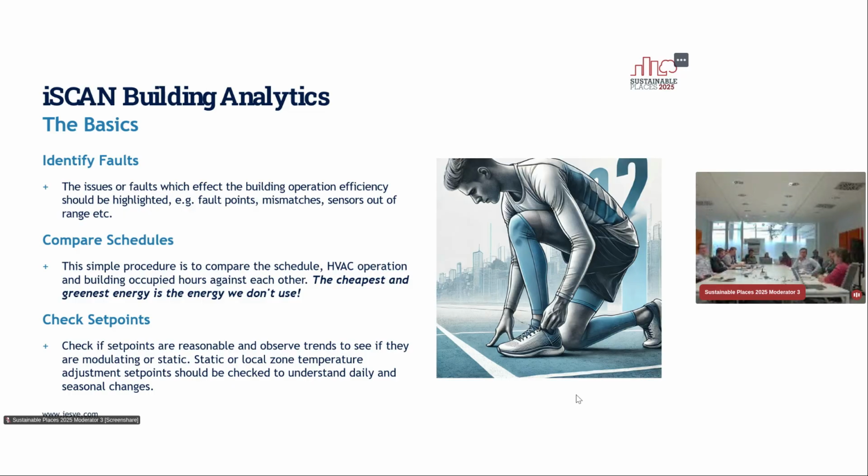There's comparing the schedules. So what's the operational schedule of the building? What's the BMS operating schedule? Do they match? There's often a mismatch there, and the cheapest and greenest energy is the energy you don't use. So there are often operational cost savings to be made there.